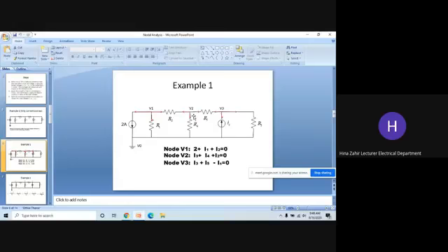These are the branches. So every branch must be covered with a current because current is going in every direction. If there was another branch at the upper side, then we would write a current going at the upper side as well. Now what about this current, which is I2? Here we wrote V1 minus V2 by R2, but now it is V2's turn. So in V2's turn, you will write V2 minus V1 divided by R2 because now we are considering V2.